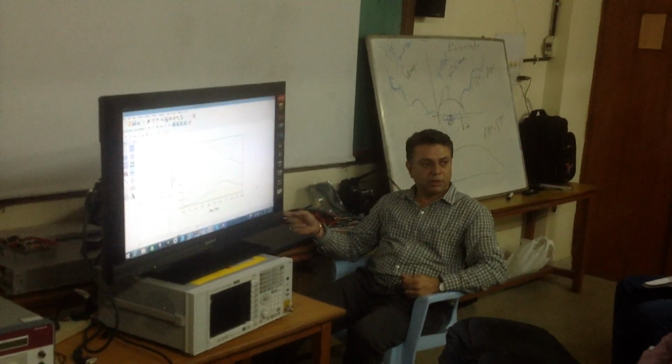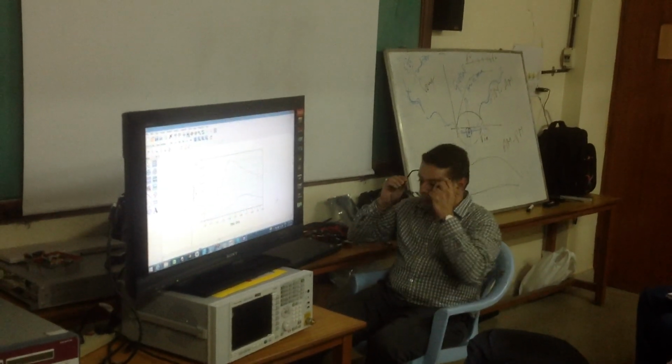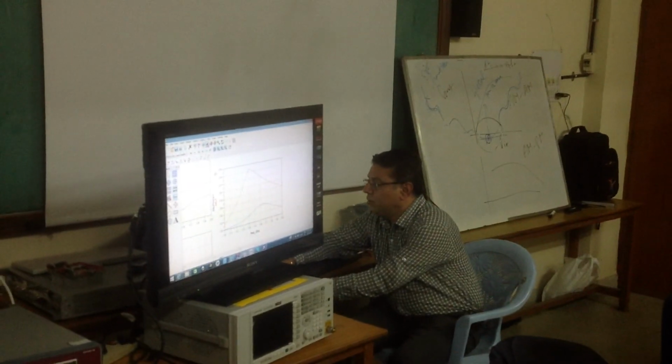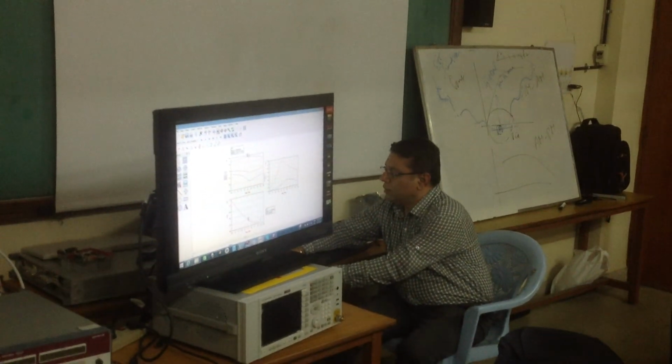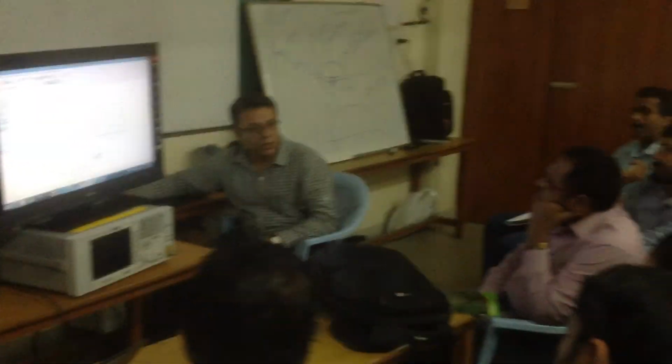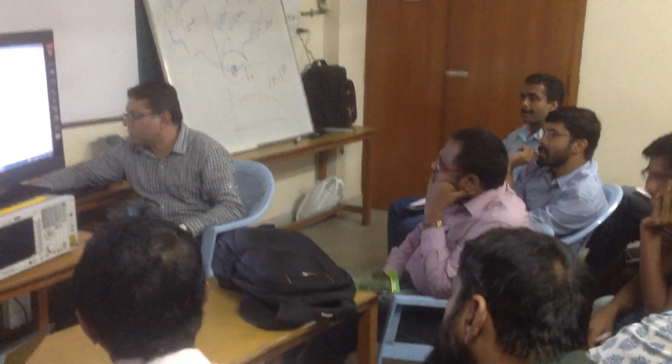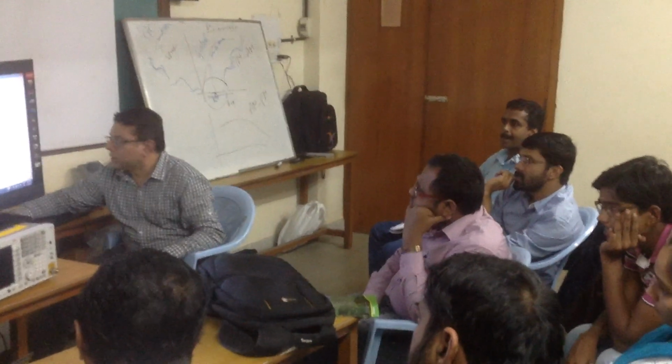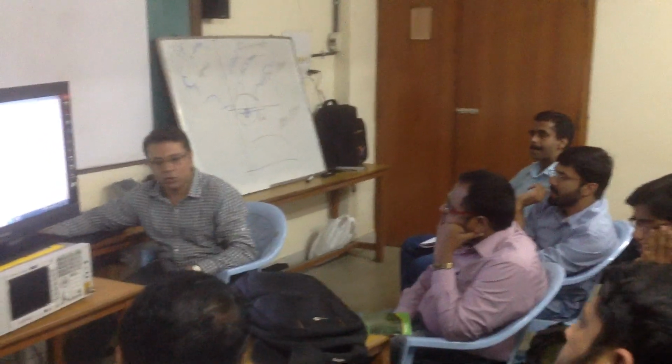Okay, what to do is clear. So now the LNA is good. Everything is fine. I have good gain matching. See the return loss now at the end. It is not good because I haven't matched it for a good return loss. I have matched it for a good noise figure.